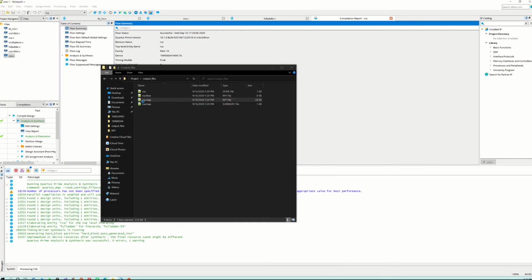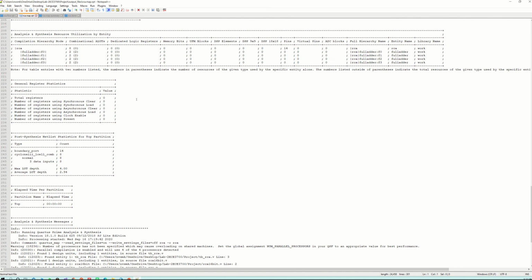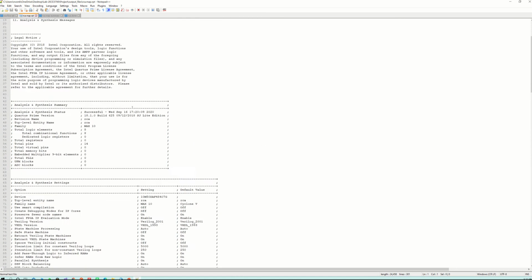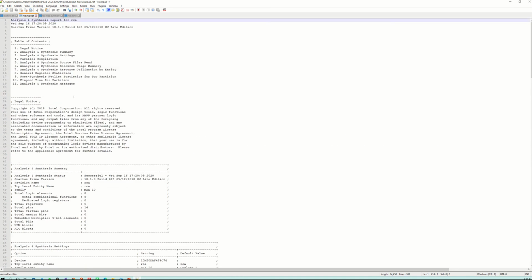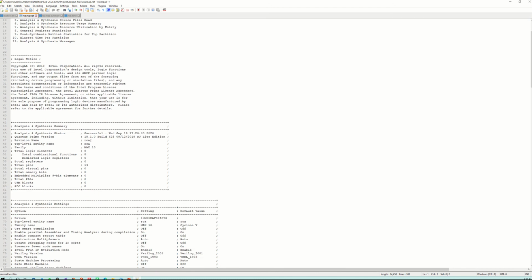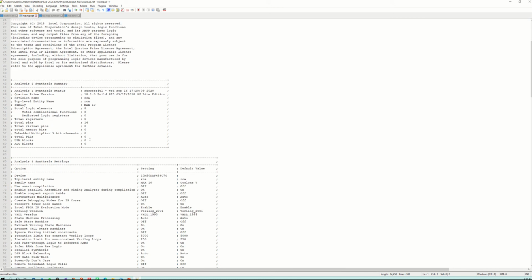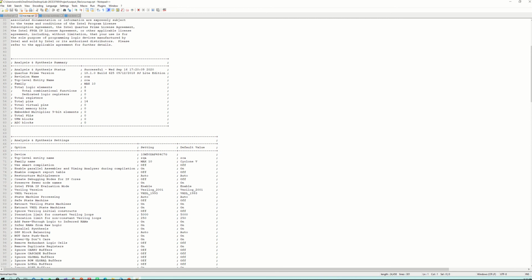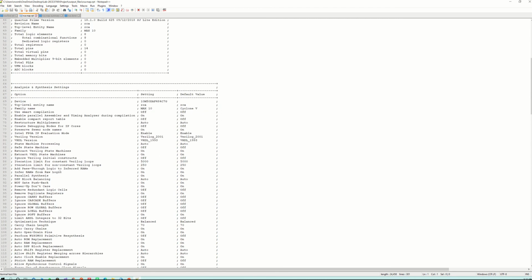Your RCA map is something interesting, something important to look at. This is a map of RCA, that is my ripple carry adder. By map, it means the way in which your elements inside are arranged. So again, my top level entity is RCA. You will have a summary of all the analysis and synthesis that is done, like the number of carry buffers used, or the RAM, if at all it is used, number of state elements used, and different things.